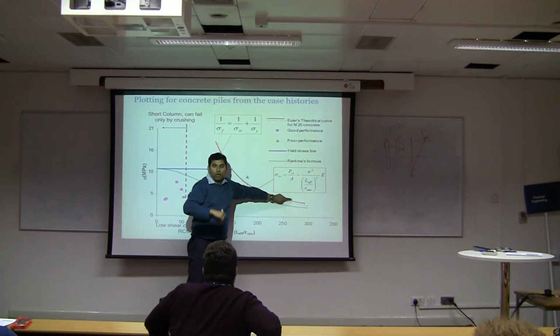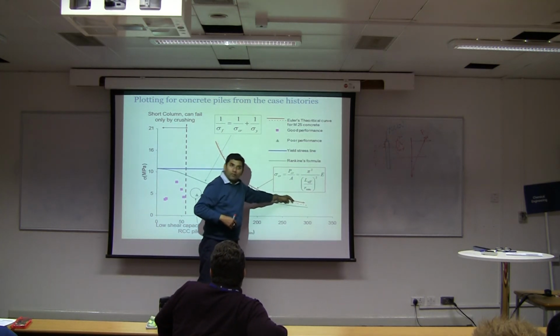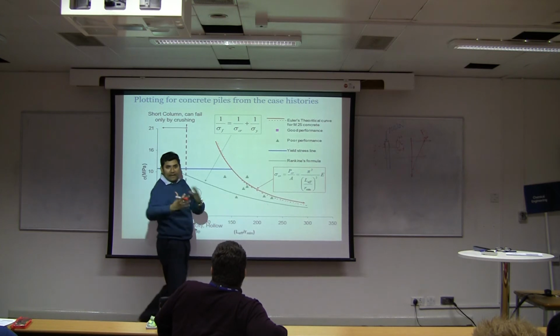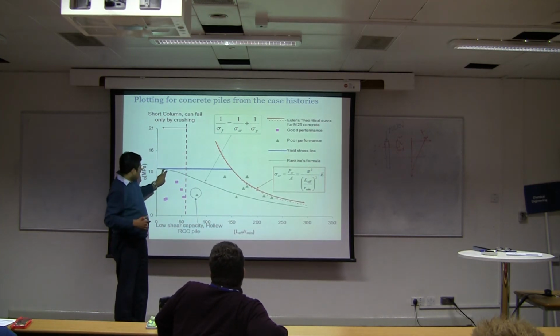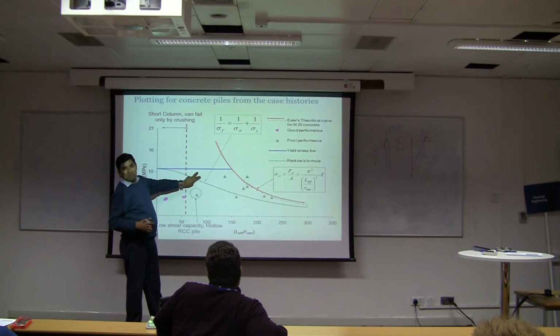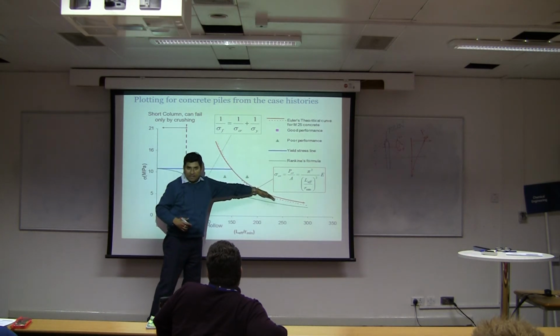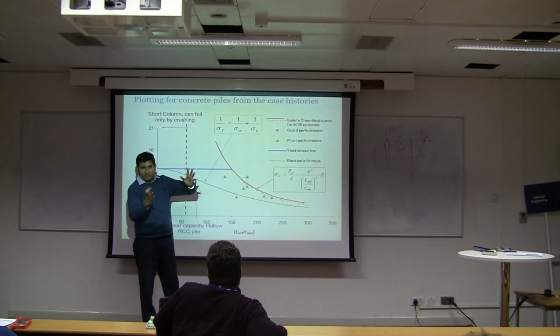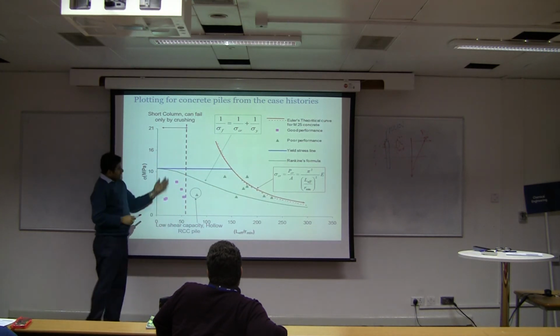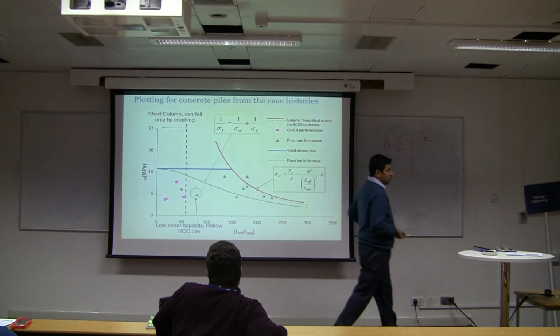And this one is the Euler formula. And actually things fail in between. So this graph, this green line, relates strength to stiffness. So that's basically a stiffness issue. So it buckles. Again, that graph shows that actually buckling was governing those pile designs.